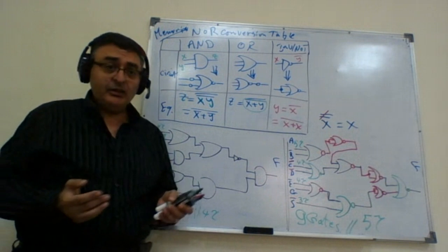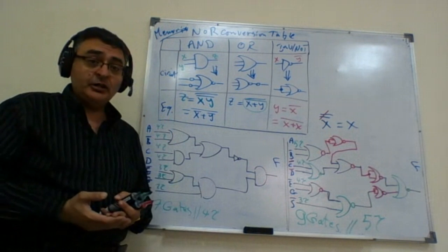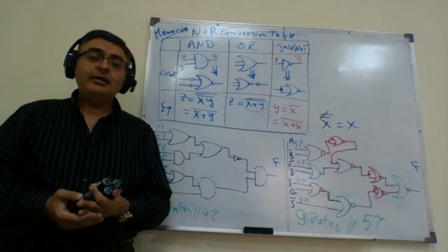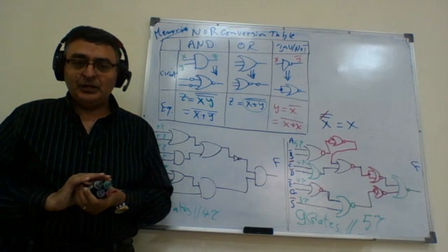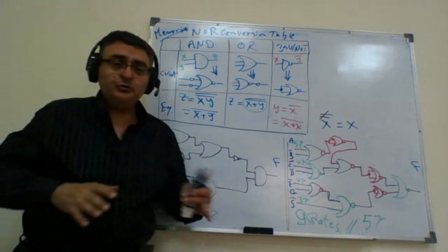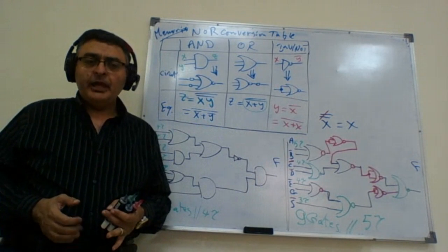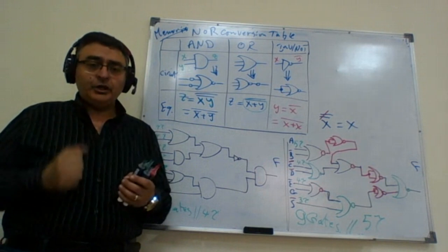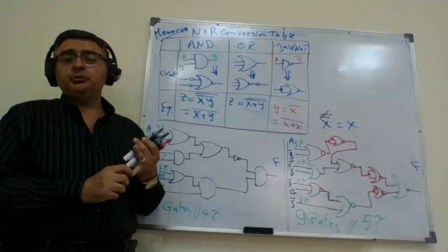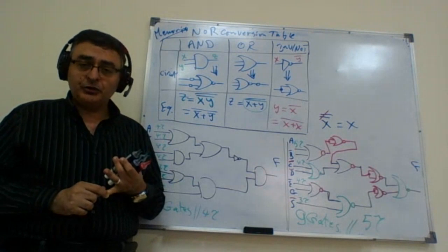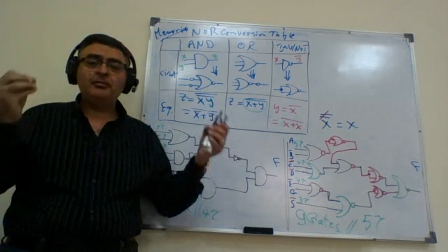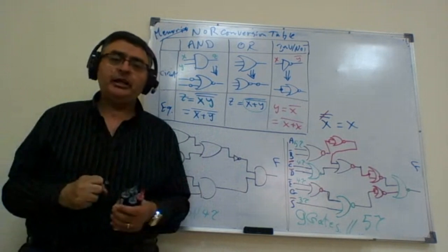Does this mean the NAND and the NOR gates are bad? Are they hurting the circuit more? The answer is not final yet, okay? So right now, to wrap things up, I can actually optimize the circuit in 3 regards. We learned in chapter 2 how to reduce the delay of the circuit. How can I achieve that? By reducing the circuit delay to the minimum delay ever, which is 2 tau delay.